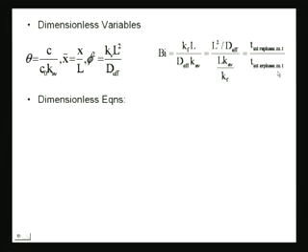So, this is a new number that we have, and you have studied this number elsewhere, but we just get back to it here. So, phi square is your ratio of diffusion to reaction, and the Biot number is the ratio of internal mass transfer time over external mass transfer time.